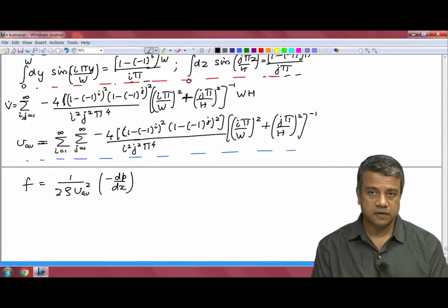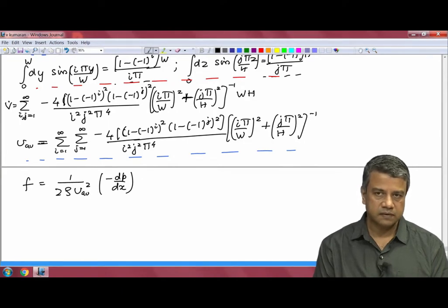This is the solution for a laminar flow. We have assumed that the Navier-Stokes equations apply, and therefore, this is a solution for the laminar flow. We did not include any convection due to turbulent fluctuations in our description. So, this is for a laminar flow.